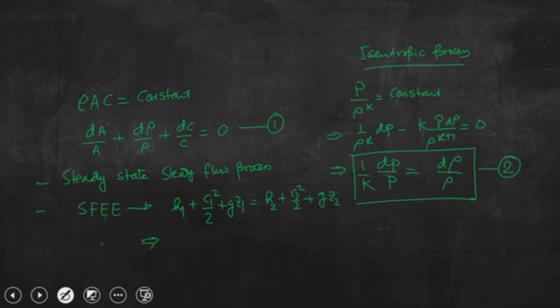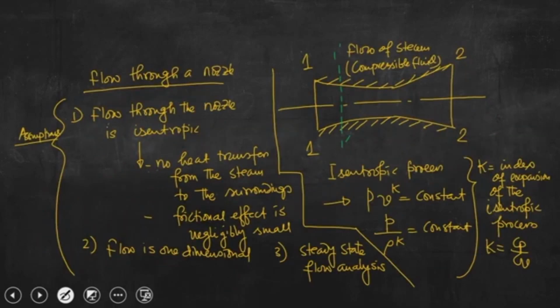Because in absence of heat and work interaction, I am writing over here the steady flow energy equation in absence of work and heat interactions. Mind it, while writing this equation, we have considered the work which is needed to maintain the flow in the presence of pressure.